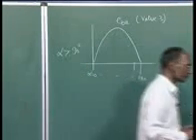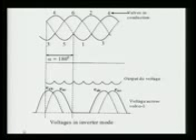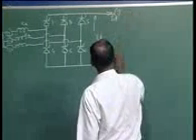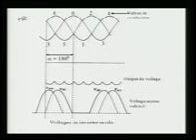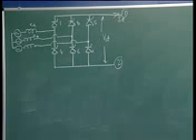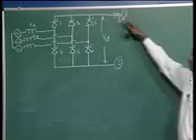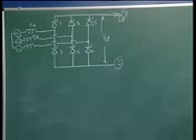Then we can get the following voltage. Here you can see the valve numbers in this figure: valves 4, 6 and 2 are conducting during that period. The first portion shows the voltage at the first terminal, the terminal of the first limb. Here is 1, here is 2, I can say top and bottom. So the upper portion shows the top voltage, and the lower one the bottom voltage, and the output voltage is this minus this, the instantaneous voltage across the link.